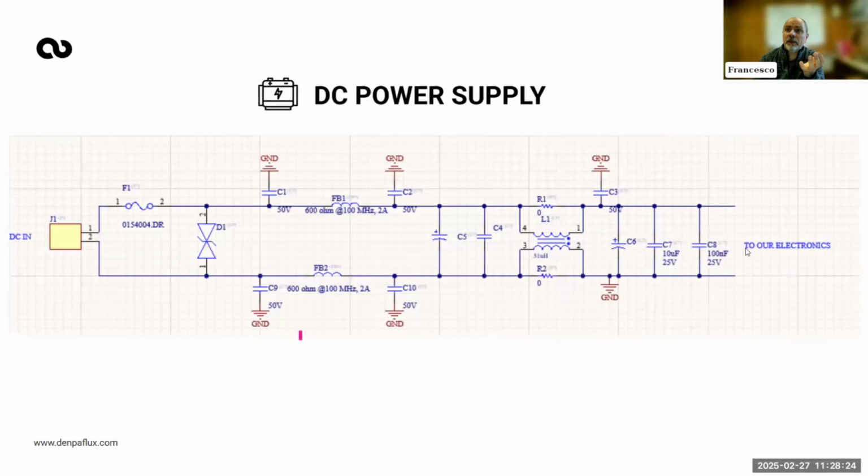So coming back to this circuit, you can see that every component that we have here has a specific functionality. D1 here is for surge and fast transient. C1 and FB1 here are for improving radiated emission above 30 megahertz.